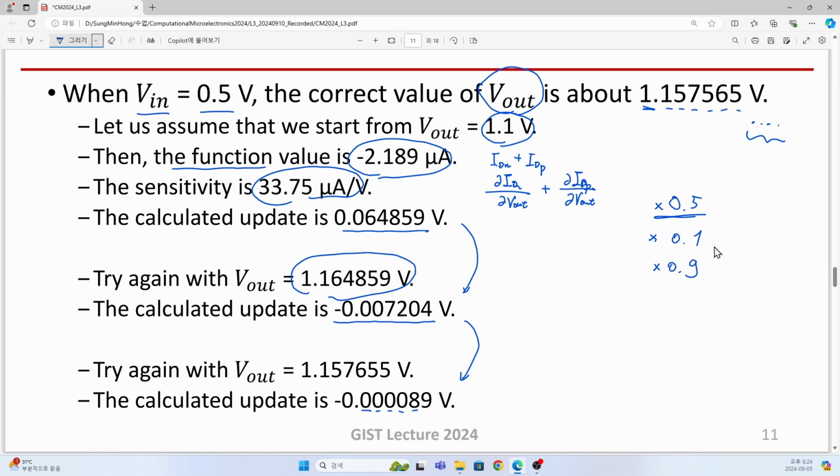However, if this is too small, then sometimes the reduction step becomes too small too rapidly. After that, you should spend more time. And if it is too large, like 0.9, then we have to go back and forth and back and forth, so too many iterations. Which one will give us the best value, or the smallest number of iterations to get a converged solution?